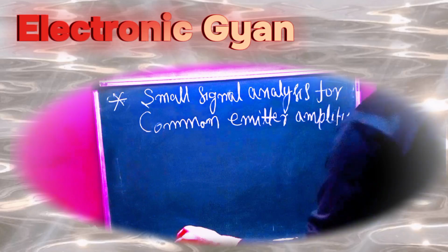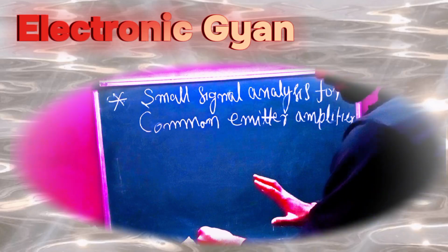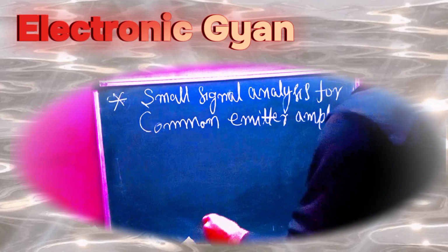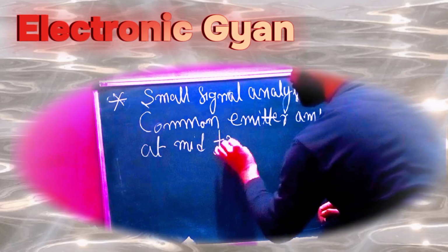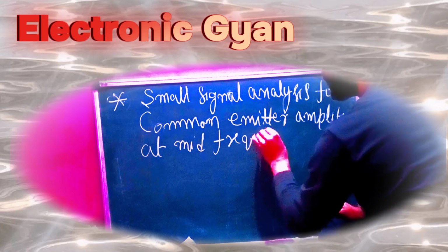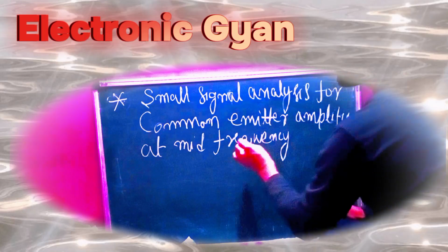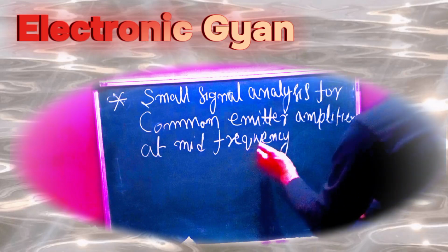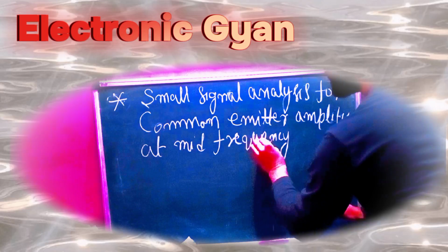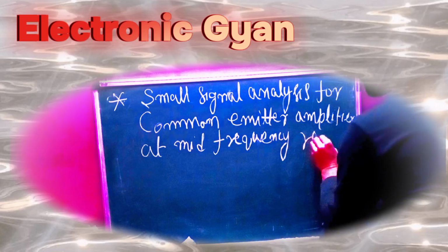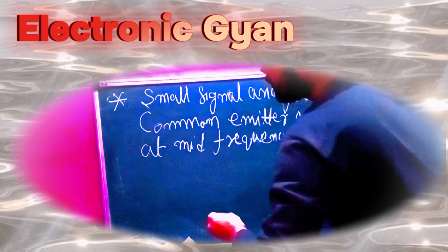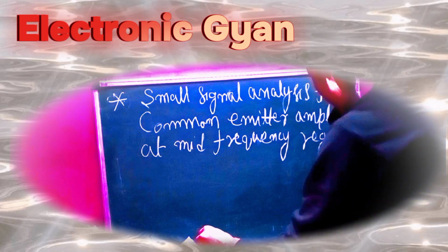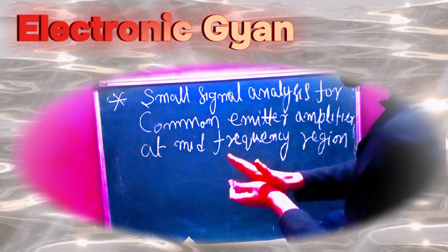In small signal analysis of the amplifier at the mid frequency region, what happens? At mid frequency region, all the coupling and bypass capacitances get short circuited.